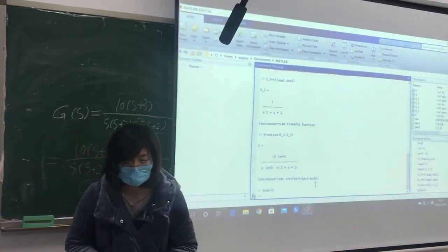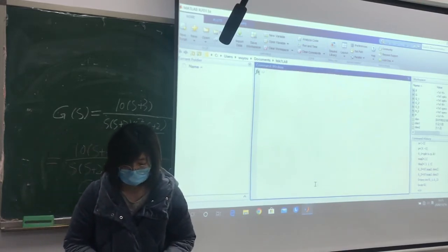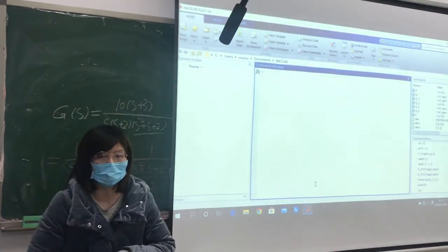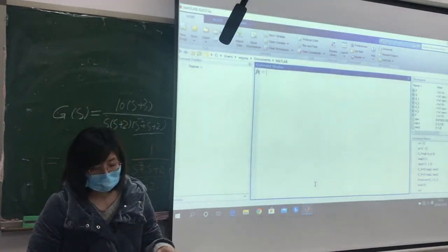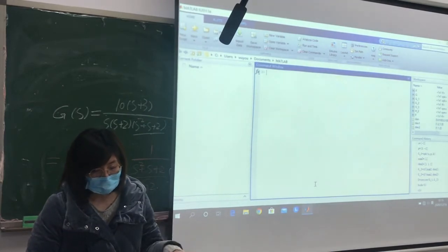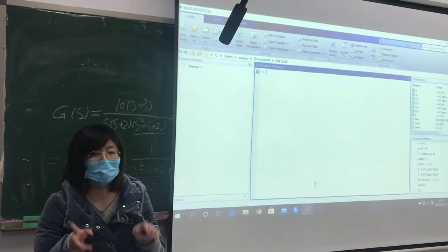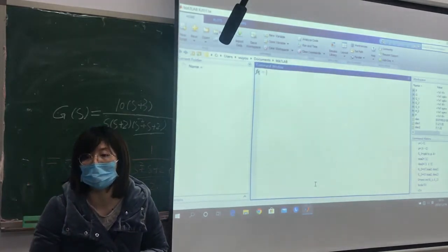So first, how to type in this transfer function. We can treat it as two systems in series. One is, we can keep the K, 1250 with s plus 2 and with denominator s squared, in transfer function 1, right?